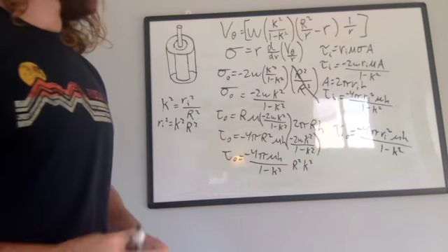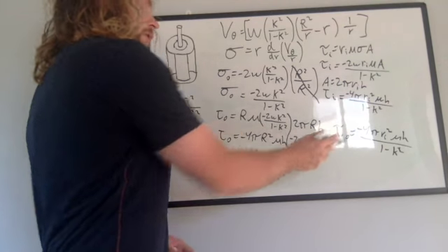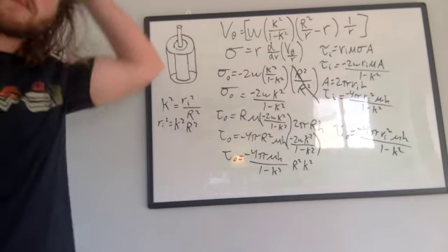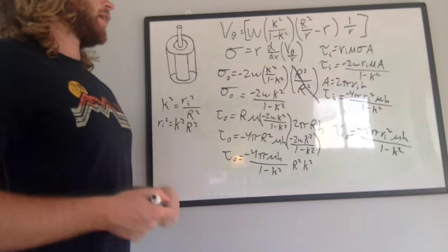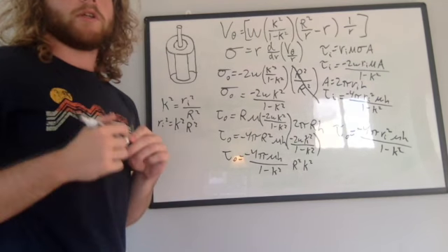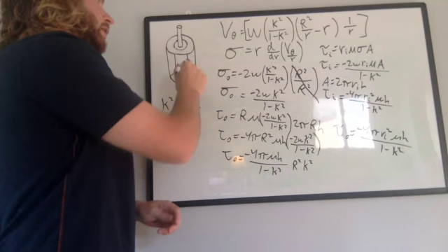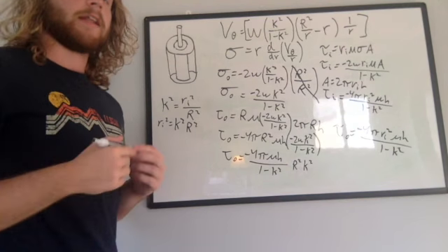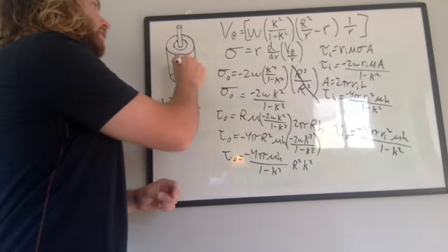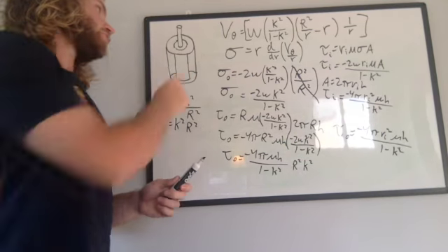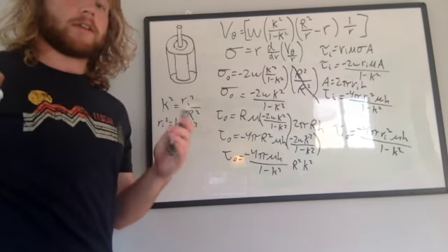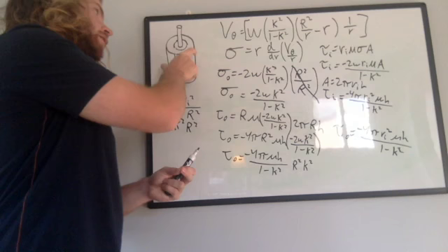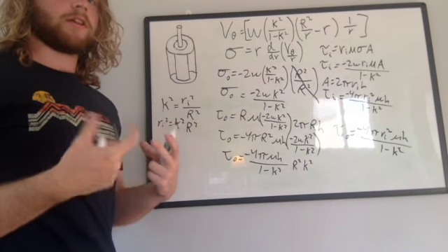As you can see, the torque on our inner cylinder and the torque on our outer cylinder is going to be exactly the same. It's the exact same expression. And pretty much what this means is that our equations up here are valid. We are going to be able to use these to represent the velocity of the Newtonian liquids between the cylinders at a given radius, all right? And again, the velocity is going to be highest at the inner cylinder, and it's going to go down as you get closer and closer to the outer radius of the outer cylinder, where the velocity is going to be 0, the same as the velocity of our outer cylinder, right? Because our outer cylinder is not moving.